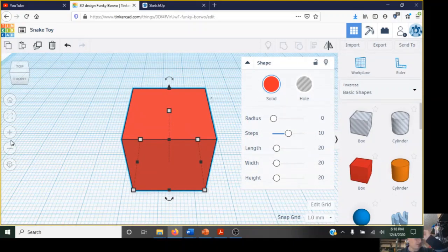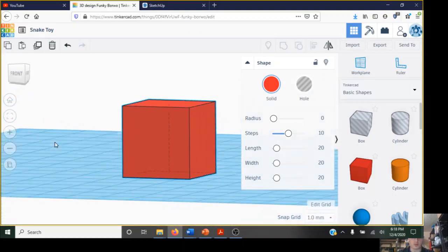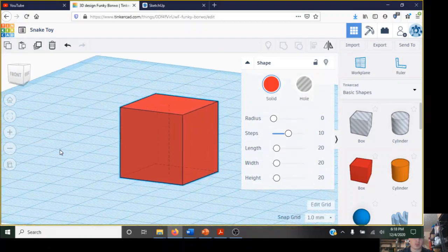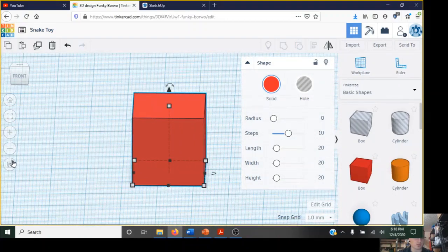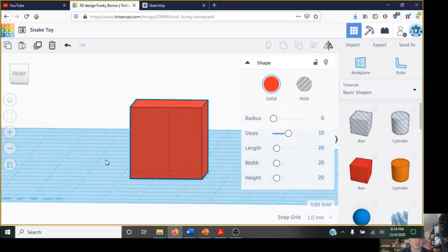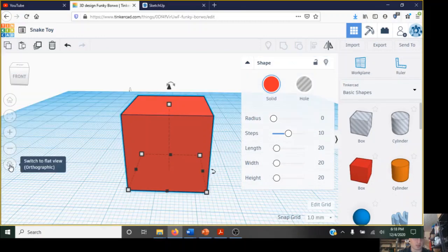Now the one thing I haven't liked about this is that it has an orthographic view. So if you click on that, you get the orthographic view, which starts looking really weird really quick if you're trying to model it. And I've had students try and do this and they've gotten really frustrated, so I'd almost wish this was actually a hidden button or something you could maybe pull up on a menu here. So it's a quirk that I've hit a couple times teaching this, where students will try and model like this and it just does not work real well. So I always leave it in perspective.